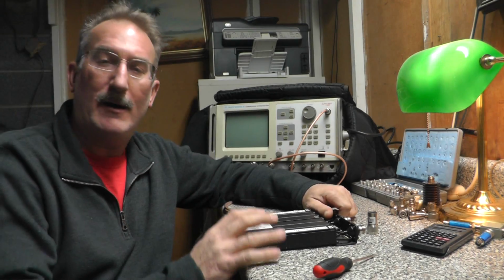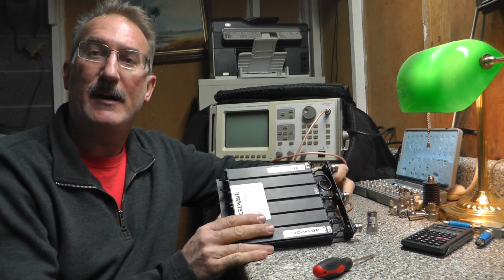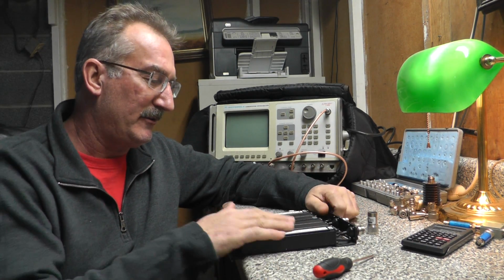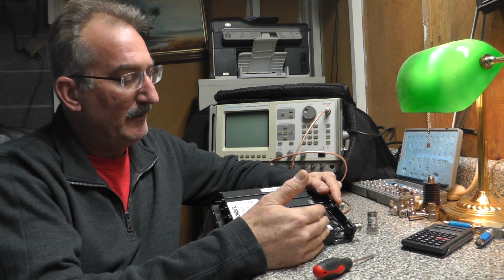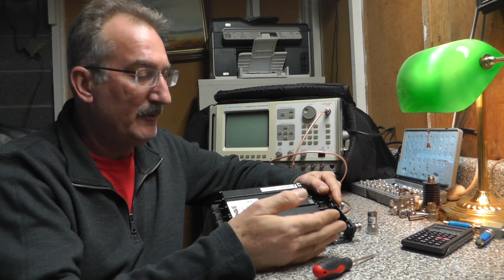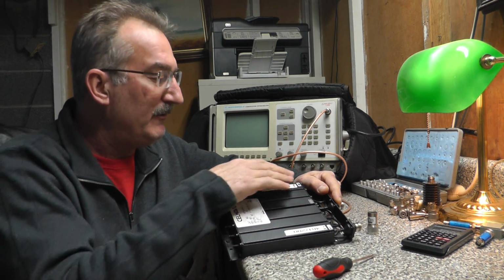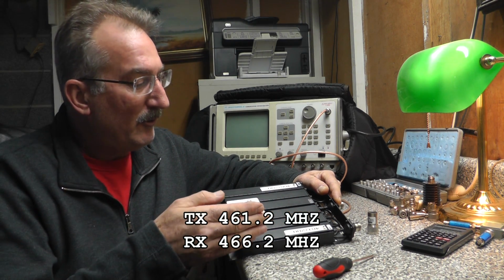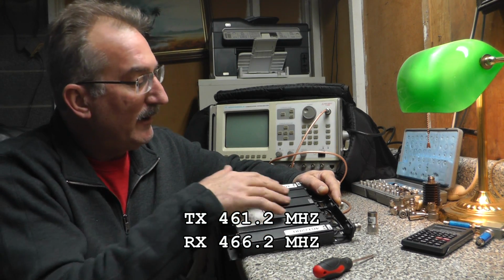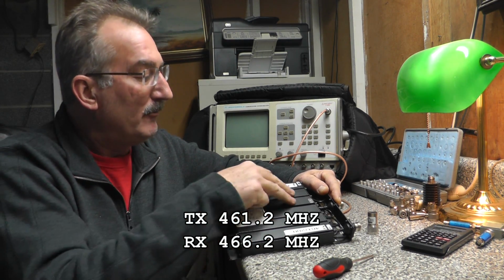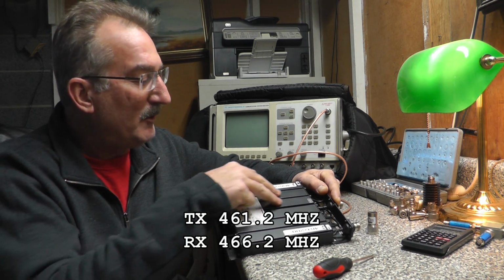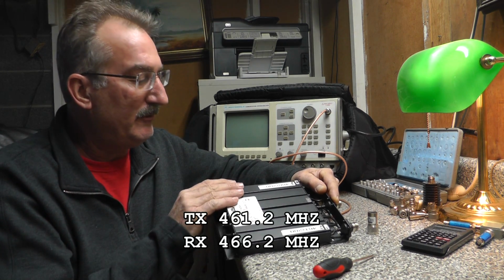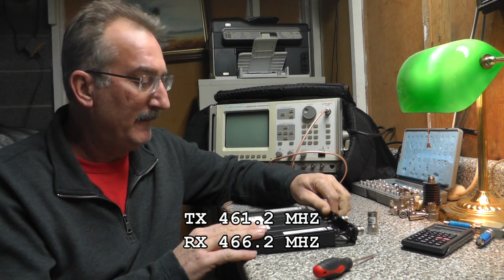I'm going to take a few minutes to show you how I've learned to tune one of these notch type duplexer filters. It's a notch type. These are not pass cavities, these are notch cavities, and essentially what we do is this is my transmit on this particular unit, which is going to be the low side, and my receive is going to be the high side, higher in frequency. This transmit cavity I'm going to tune so that the transmitter does not transmit any noise at the receiver frequency, and this receiver side notch I'm going to tune so none of the transmitter power can pass through this filter into the receiver, and it'll make more sense as we go along.